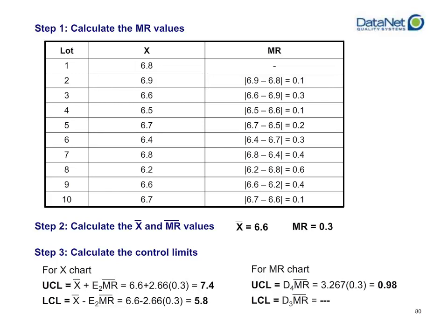Step 3, calculate the control limits just like you did for your X bar and R charts. The calculations are exactly the same, except you're using a different set of constants because your subgroup size and your subrange size is different. In this case, we're using what's referred to as a subrange size of 2.